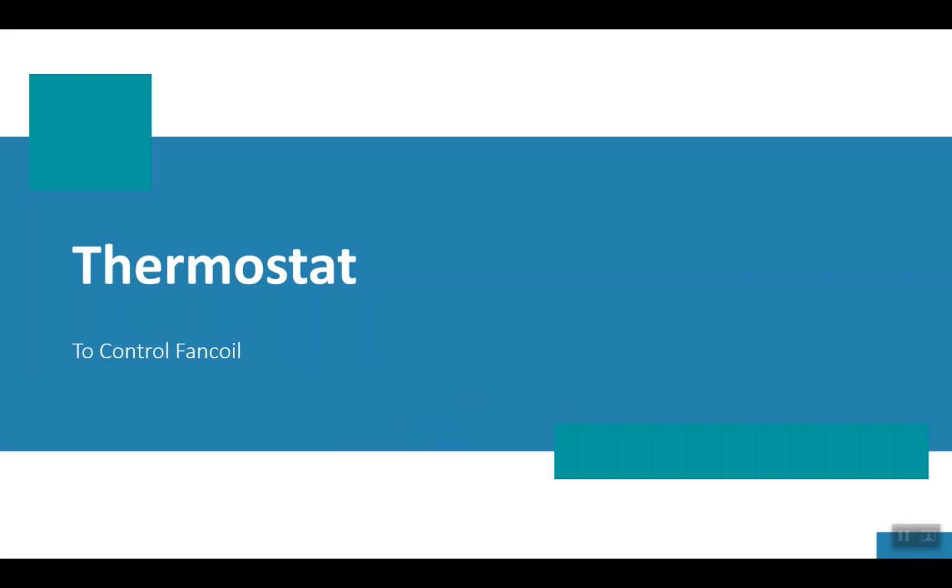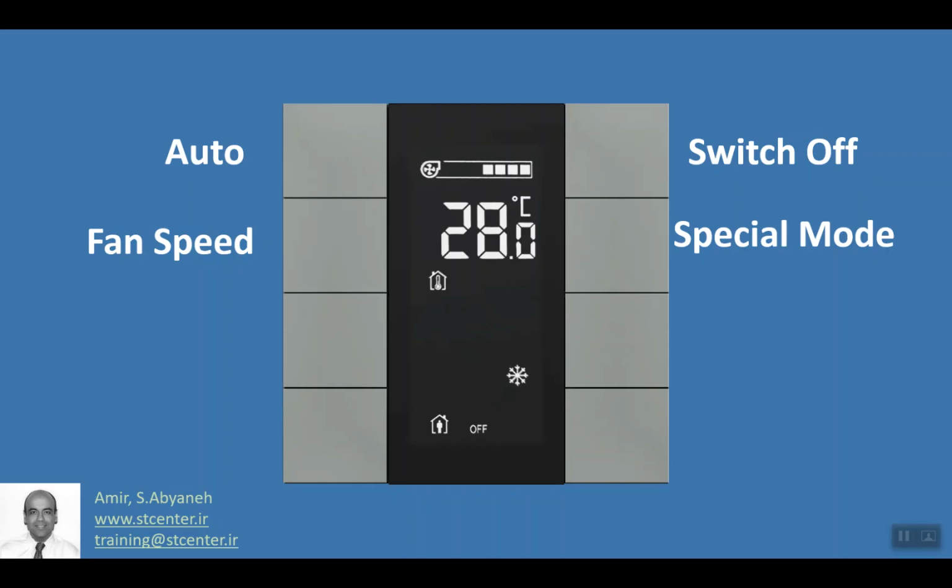In this course, I'm going to tell you how to control the fan coil 3-speed 2-pipe with the thermostat. This is a thermostat from Interra we have in this example. With button number 1, I'm going to call the automatic mode to control the fan coil. In this way, the PI controller works automatically to compare the set point and current room temperature based on the season and sends the adequate control value to the actuator. So button number 1 calls the automatic mode.